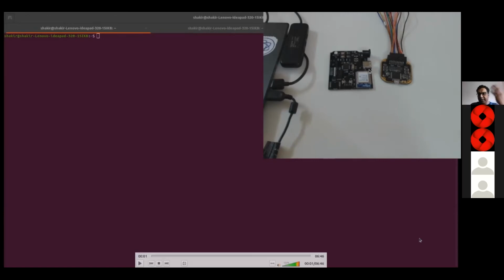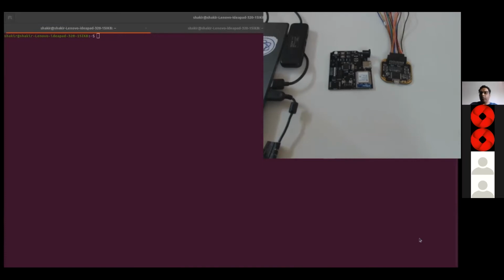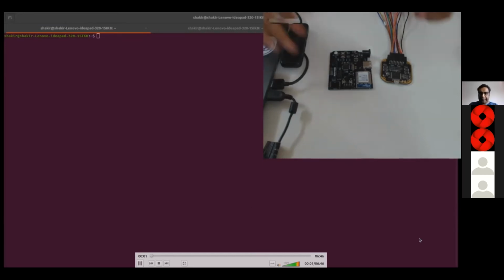It also has a ZigBee kind of protocol, right? Here we have some I2C peripherals. At the moment, we have this Bus Auditor. With this Bus Auditor, we will determine which pins are I2C and what their numbers are, right? So let's begin with that.